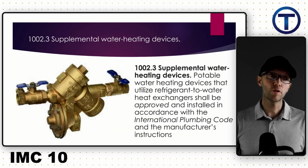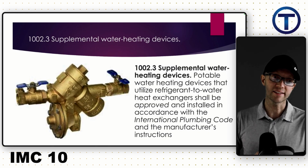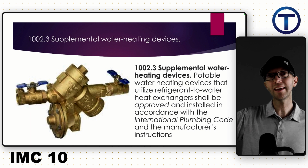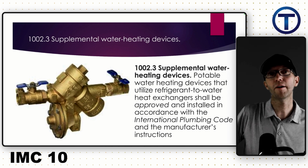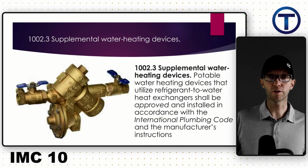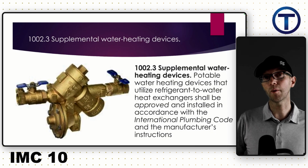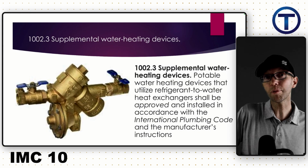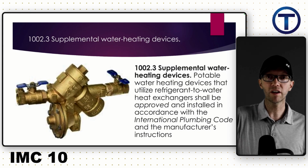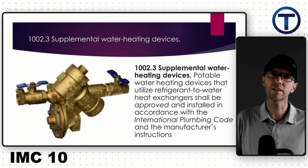Moving on to 1002.3, supplemental water heating devices. Supplemental meaning that you're bringing in heat from something else just to help out. Here's an example. If I have some solar collectors on the roof that I can use to heat water, and I can transfer that hot water down to my water heater, that can supplement or help that hot water so that I'm not relying just on electricity or gas to heat it. I'm bringing in another source that doesn't cost as much.